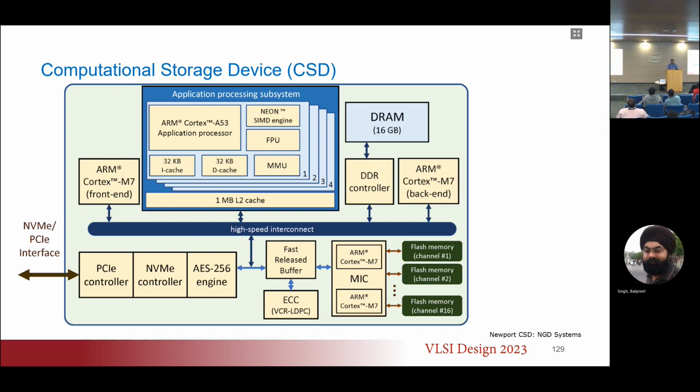Maybe we want to do the processing in the SSD itself. In a company called NGD Systems, in the SSD you have a bunch of flash memory, which is a number of flash memory chips organized as channels. So you have 16 flash memory channels, and then they do a custom design of an ARM CPU, which sits inside the SSD.